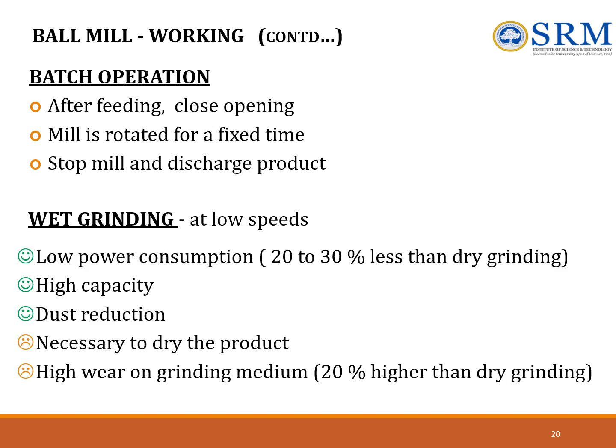Again, coming to the working of the ball mill in batch operation, as I said, in a batch operation the outlet is closed and the inlet is also closed, and it rotates for quite some amount of time given for the size reduction, and the mill is stopped and the product is taken out.